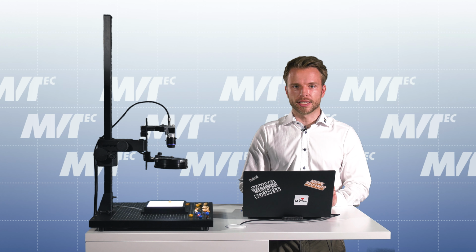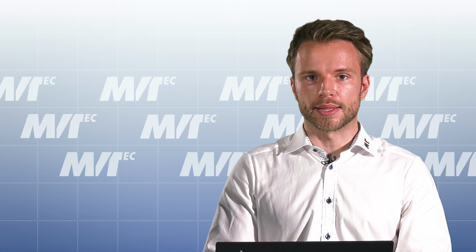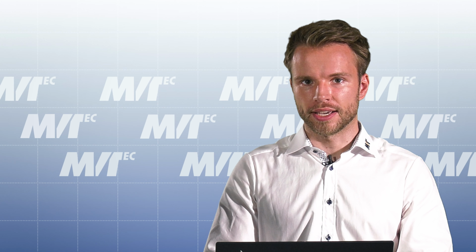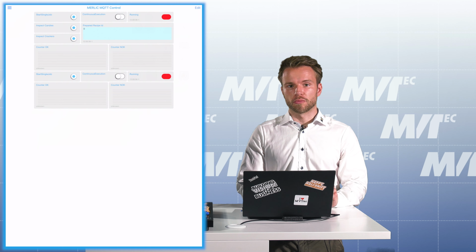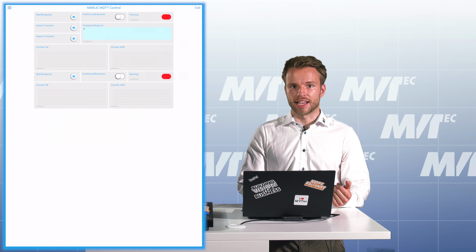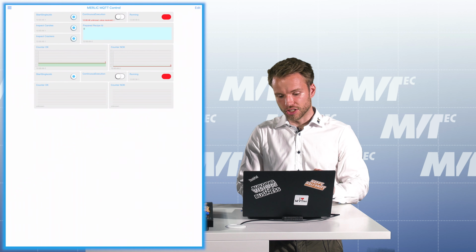But as said in the beginning, we would like to control our MERLIC vision application from a tablet. Therefore, I prepared a small application. It is called IoT On-Off. You can download this application in the iOS App Store. It is freely available, and you can configure it by yourself. Here on this dashboard you can see sliders, buttons and graphs, and they are all connected to the Mqtt Broker. So we are using the MERLIC/action/JSON topic to start a single execution.